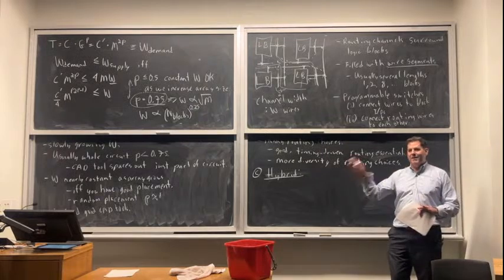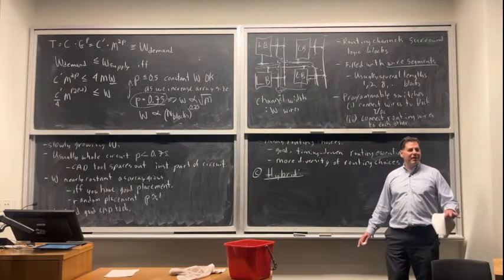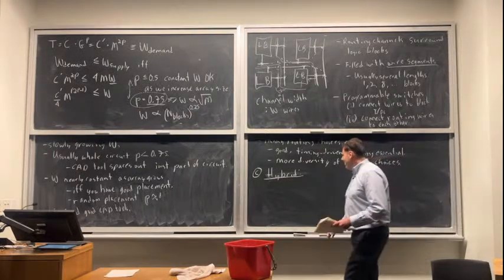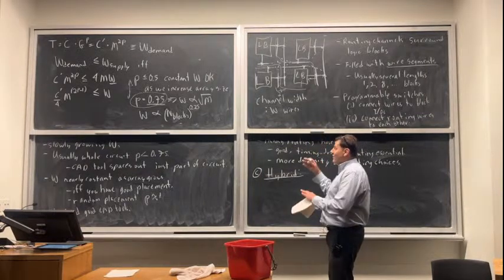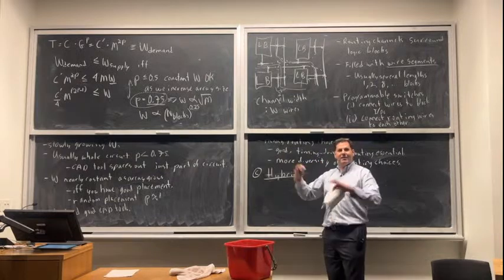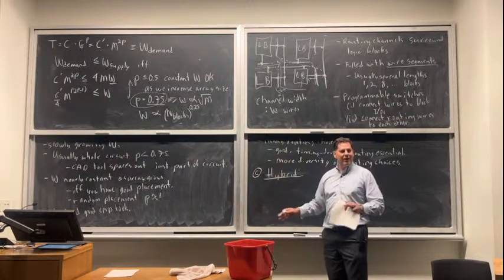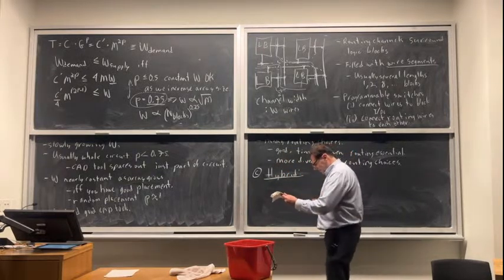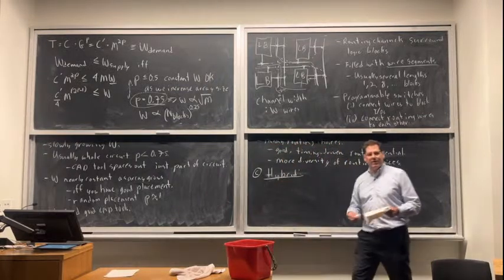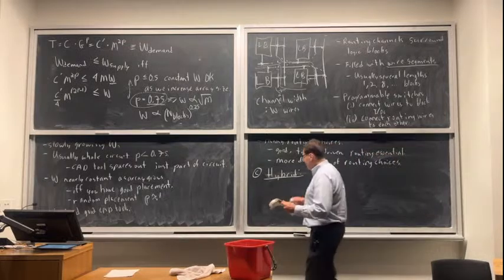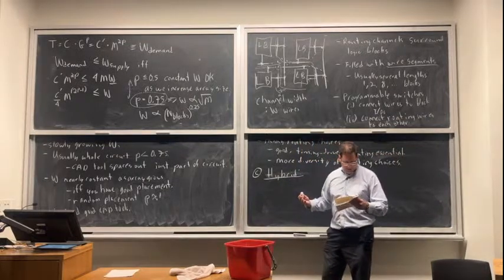We've got a very expensive ASIC or an extremely inflexible FPGA. So yeah, the one where we make small island-style FPGAs and connect them in hierarchical routing would be like an amphibious car. You don't want that. But this one works. Okay, so the advantage of hierarchical is we get simpler CAD, but the disadvantage is we had poor scalability.